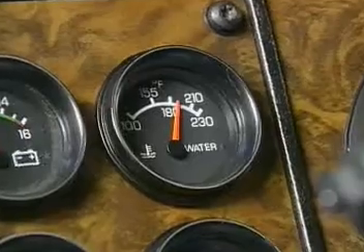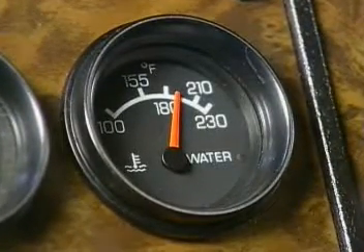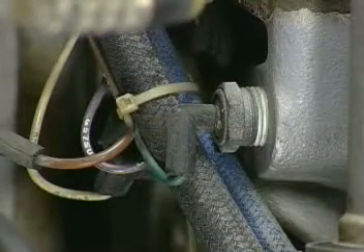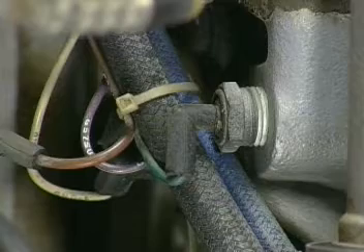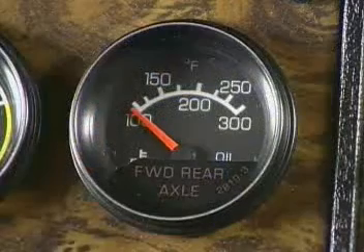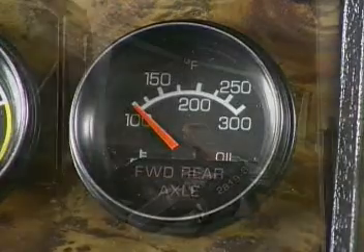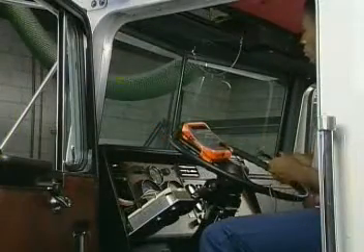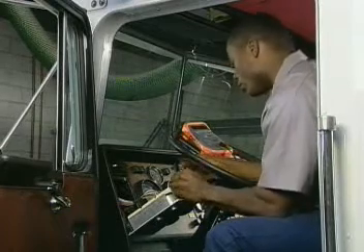Temperature-sensitive gauges such as coolant temperature, oil temperature, transmission temperature, and exhaust temperature gauges use variable resistance sensors to send varying voltage signals based on operating conditions. These gauges should change as the engine operation conditions change. Open gauge circuits will result in no voltage at the gauge and a low reading that does not change.